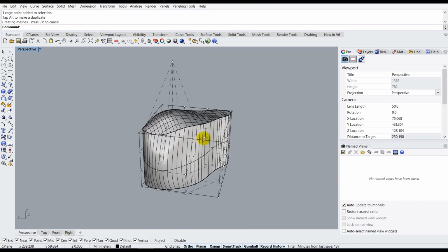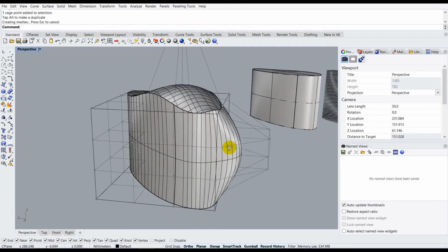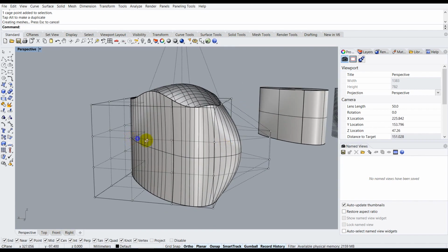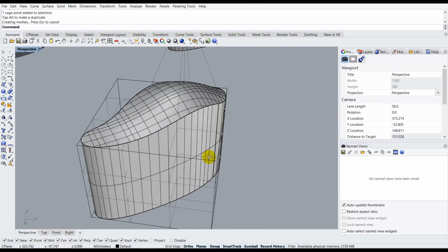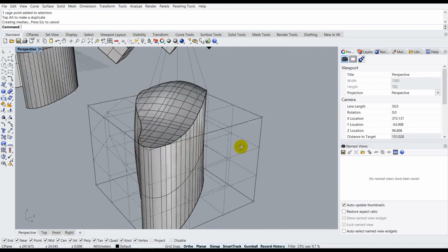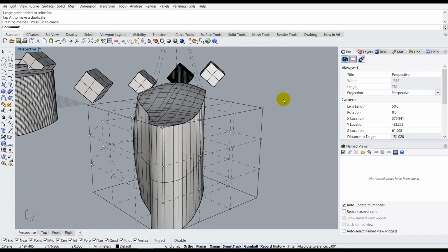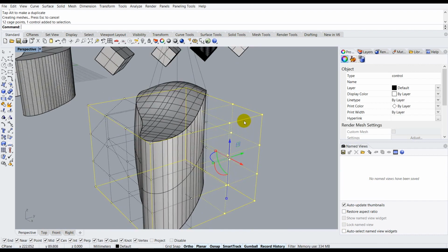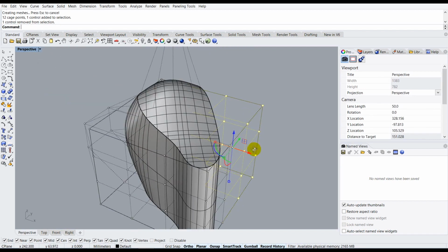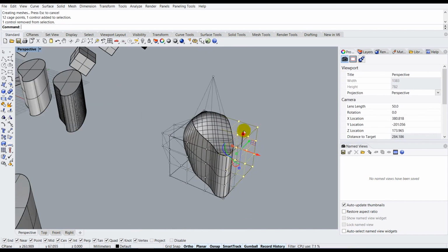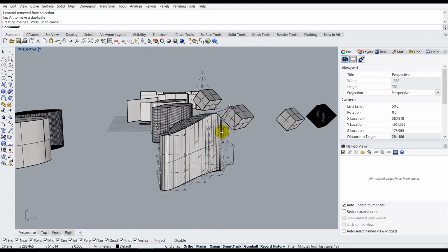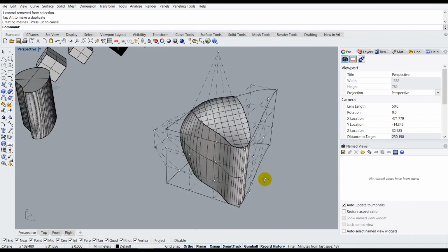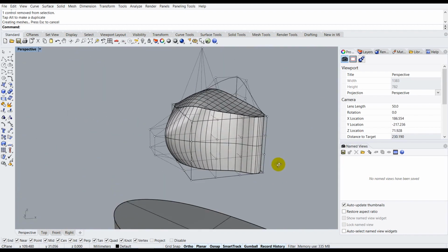See how it works. So this is cage editing in Rhino. You can play around with these kinds of parameters and see what kind of shape you can achieve. What if I select this entire point system over here? To deselect something, hold Control and click on it once again. If you select all these points and move them like this, you can see the entire thing deforms according to the way you move the points.